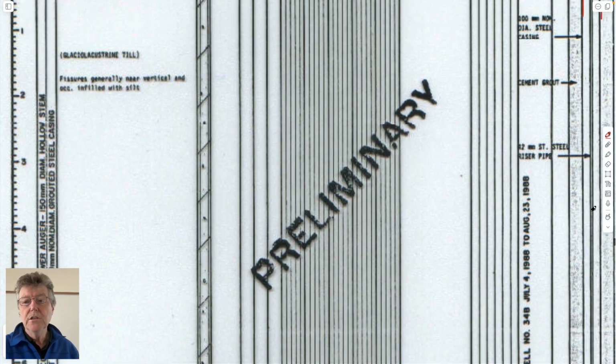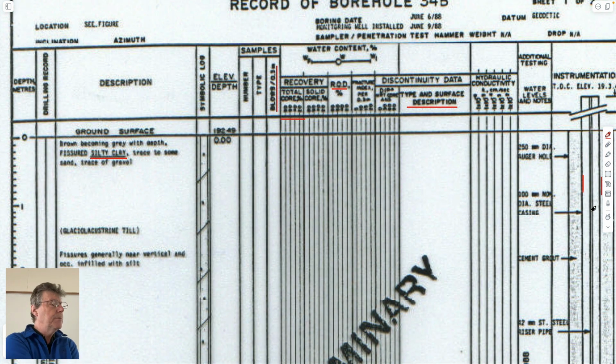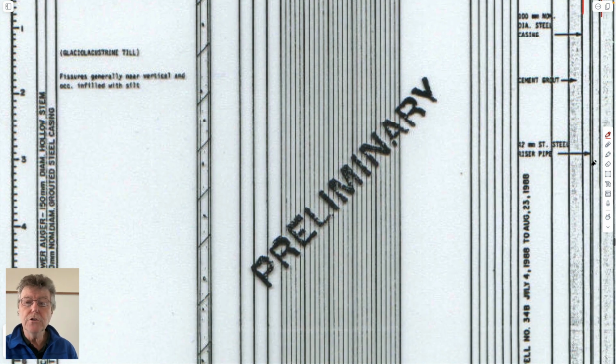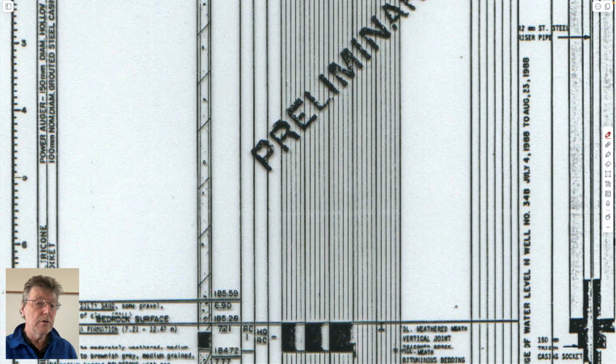So if in your GSci 452 class you talked about using slug tests or equivalent tests, all it is is that you fill up this pipe an extra foot above its static level, you count how long it takes to go down to the resting water level, and you use the rate at which it declines as a measure of the permeability. The faster it goes down, the higher the permeability, and you can calculate that pretty simply from some straightforward closed-form equations.